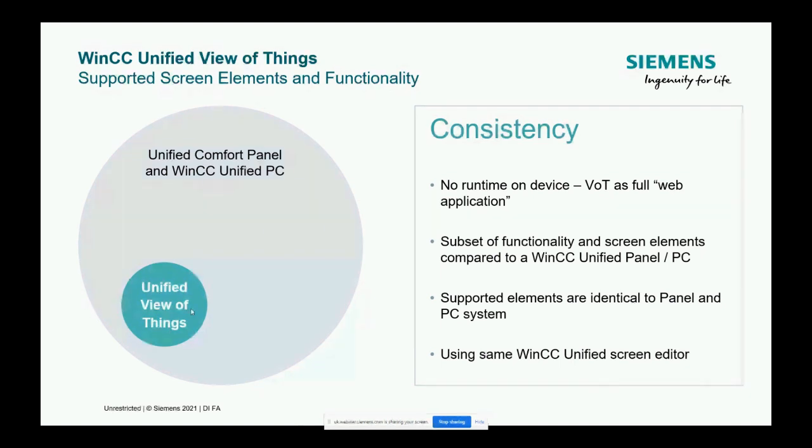We don't run the runtime on the PLC. This is purely based on the web server. We only support a subset of the functionality and screen elements compared to a full WinCC Unified system, and I'll show you what these are. But the elements that we do support are exactly identical to the HMI panel and the PC-based system itself.